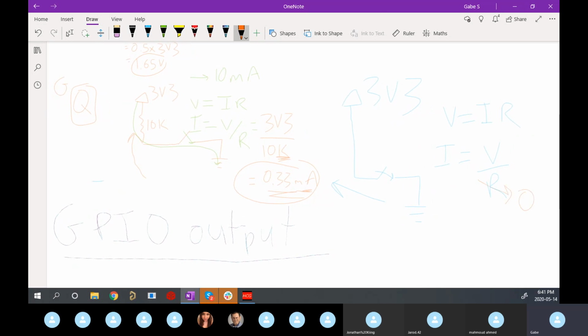If we just have a wire inside of our resistance, remember a resistor resists flow of current, right? It's adding something to block that flow. So if I get rid of it, I've basically opened up that flow of current enormously, and that resistance is only the resistance left in the wire, which is almost negligible. And so if I connect 3v3 straight through, no resistance, to ground, my current becomes infinite,